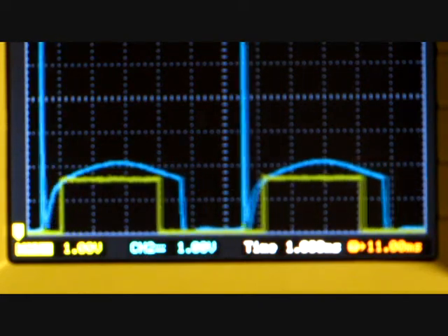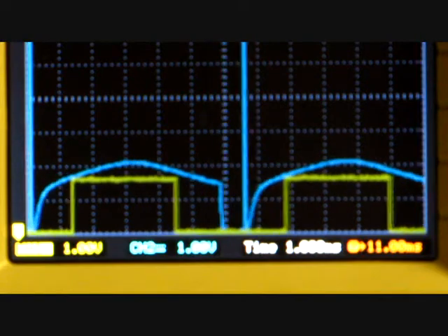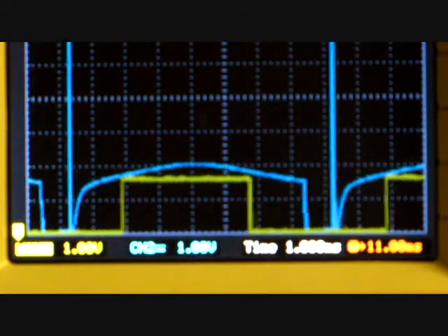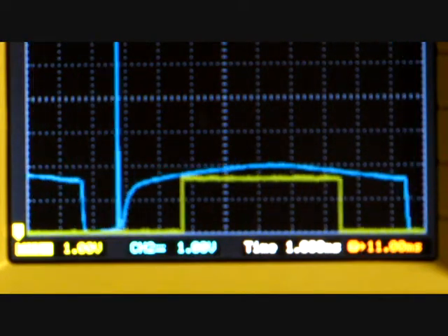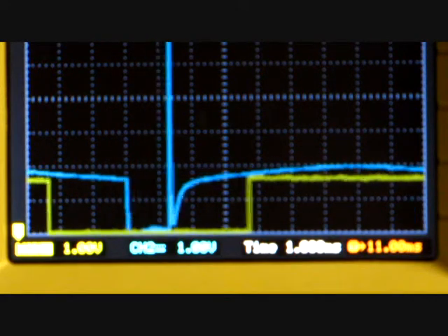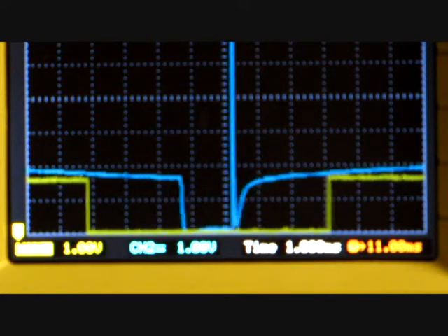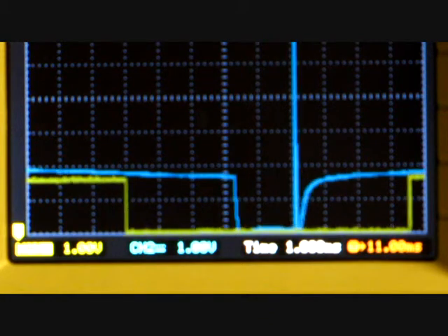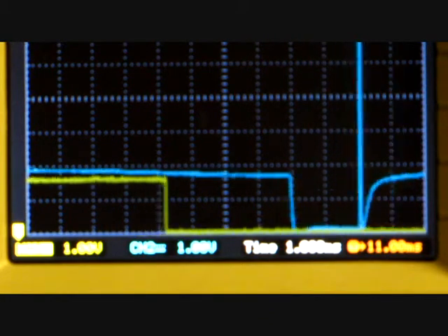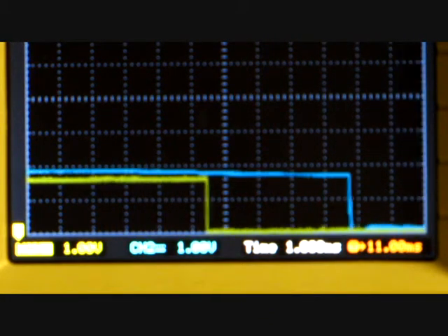There we go. I'm going to take it back down. You notice how it stays in the center there because of the automatic delay. If I had that turned off, it'd be jumping around. So the automatic delay adjusted itself to 19.5% right now.